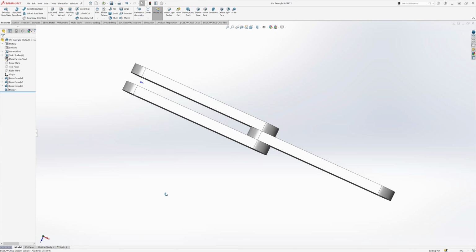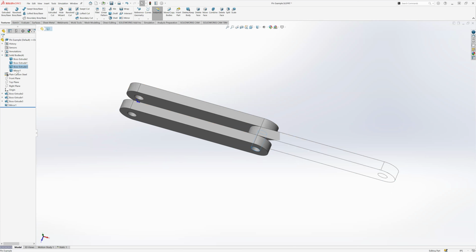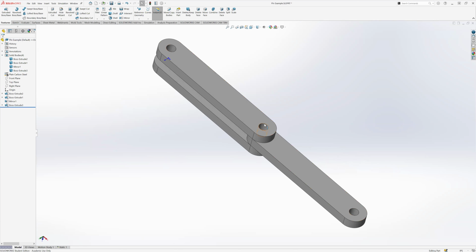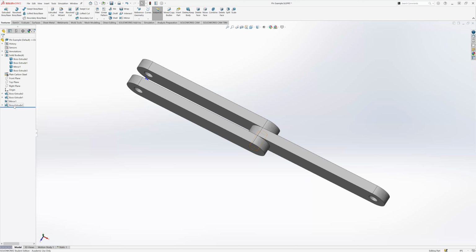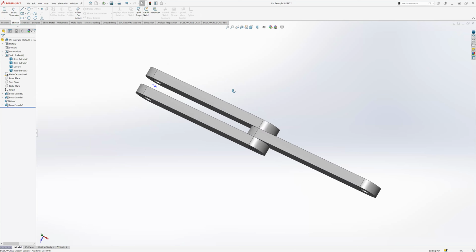Okay, so we'll go ahead and do that real quick. Now we've got four solid bodies. Obviously we've got that component, we've got these two, and then the pin. One thing here real quick, I'm going to reorder features again because I want the pin to be last. I want this pin to go all the way through. I don't want the pin to just stop right there. So I'm going to grab this again and switch the face here. Instead of extruding up to here, I want to extrude all the way to there. That should be a quick thing, very similar to how I did it earlier.